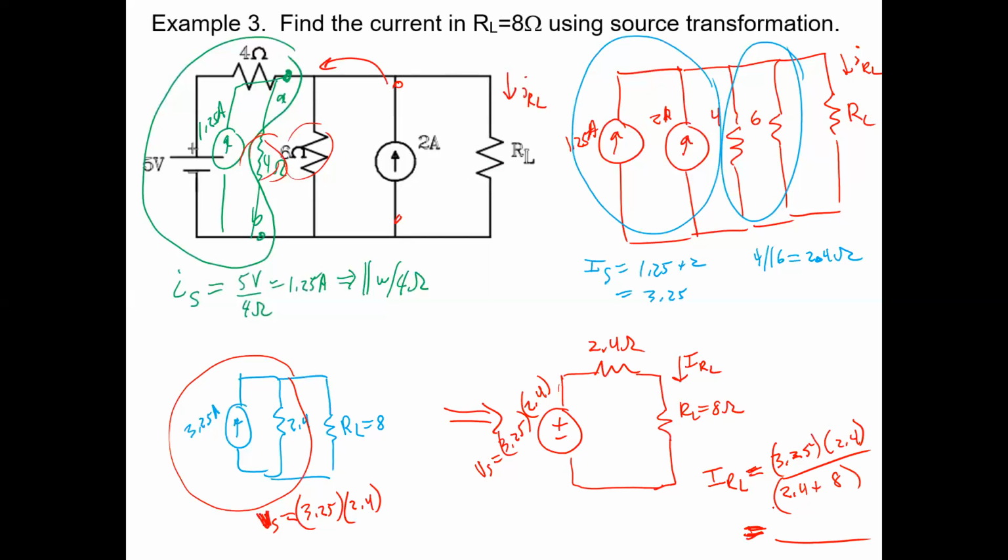Again, we're just learning these additional tools. Superposition was one of them we did yesterday. This is source transforms, getting us thinking about equivalent circuits. These are equivalent at these two nodes where they are connected to the rest of the circuit. The rest of the circuit doesn't care if you replace them with one or the other form of those two circuits, as long as they have the same equivalent behavior at those two terminals, A and B.